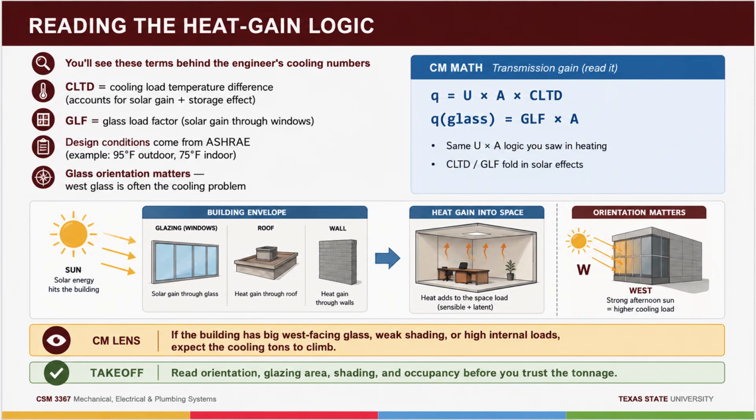People, 30 times 900, 27,000 BTUs per hour. 30 exercisers heat like 60 office workers. Occupancy type matters as much as head count. Ventilation airflow, 30 people at 20 CFM is 600 CFM.